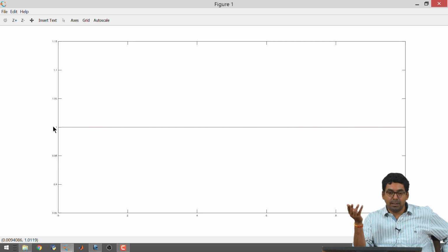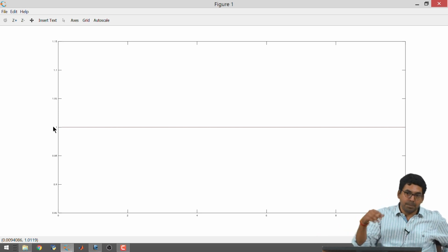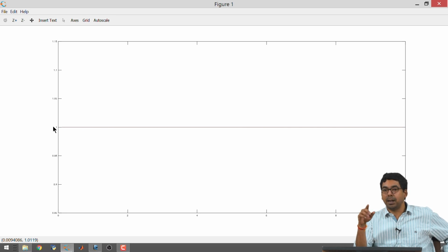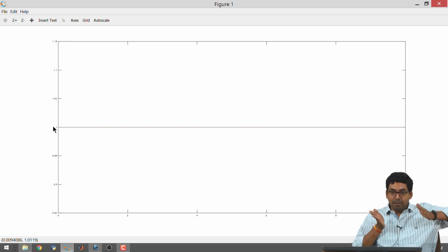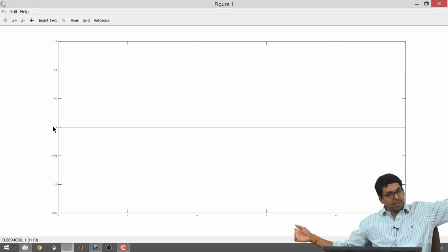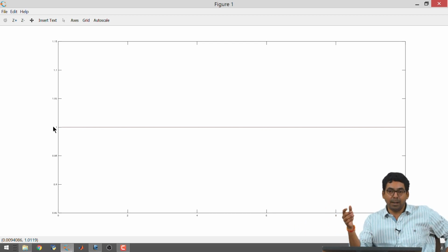So, what does this mean? This means that even though you can write down the fundamental mode of a parallel plate waveguide to be M equal to 0, it corresponds to a case where there is no component of electric and magnetic field along the direction of travel. It represents a pure plane wave, and the waveguide does nothing to it, which means the intrinsic impedance of the waveguide is equal to the intrinsic impedance of air; it does not reflect, does not scatter. That means that even though you have kept two infinitely long sheets in vacuum and you are launching a plane wave, the plane wave does not see it. It just sees the waveguide to be purely transparent.